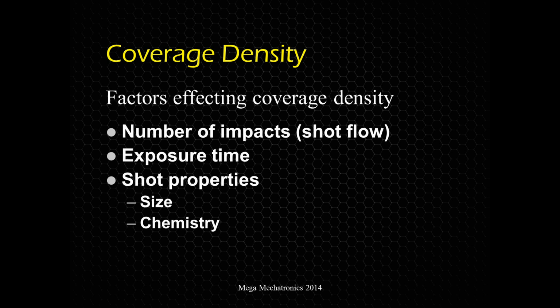And density is also affected by the shot properties, the size of the shot and the chemistry makeup, like the hardness of that shot, and whether it's ceramic or cast. And workpiece properties. How hard is it? It's going to take longer to get a good coverage on a harder material, workpiece.